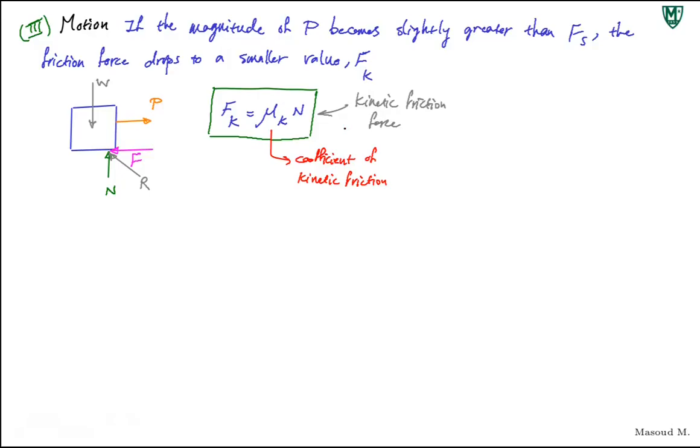And also the same story, you have this angle. The reactive force creates an angle with the normal force, you can call it phi k, and the value for phi k we can find as tan inverse of whatever is the opposite, which is Fk, over N. So tan inverse of mu k N over N. That means phi k is tan inverse mu k.